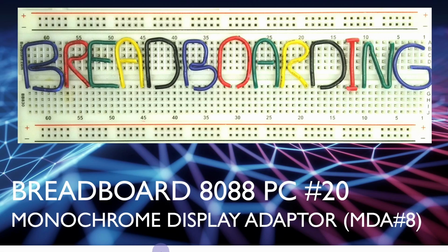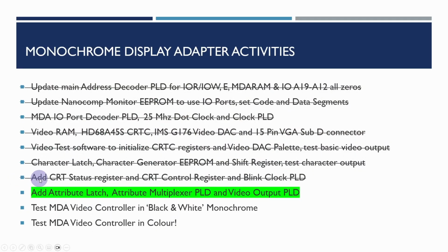Welcome to Breadboarding. This is video 20 in the Breadboard 8088 PC series, and it's also the 8th in the series looking at building out a Monochrome Display Adaptor video controller which is compatible with the original IBM PC. So in the previous video we added the CRT status and control registers and also the blink clock necessary to generate the signals for the cursor and the character blinking.